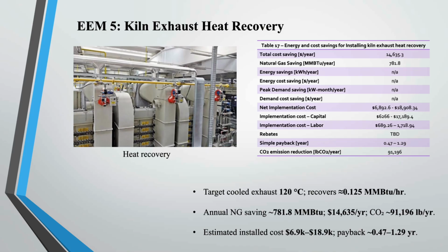Our final measure targets the furnace exhaust heat recovery. Currently, the hot gas leaves the stack as waste. For the solution, we propose installing a heat exchanger. Our target is to cool down the exhaust to 120 degrees Celsius. This allows us to recover the heat safely without causing damage to the stack.